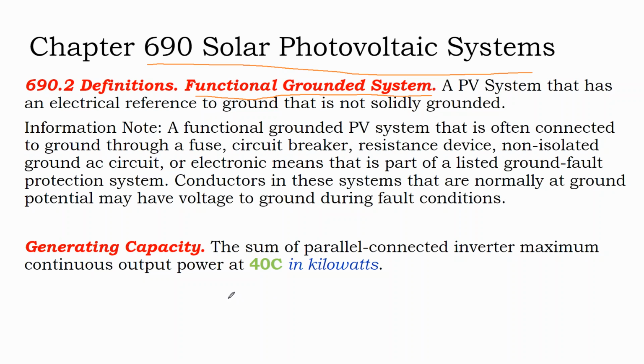Well, on a DC circuit, you would have a positive side and a negative side, and it's quite common to tie that negative side to ground so that the negative side has a voltage potential of 0 and the positive side has a voltage potential of 12. And so they'd say, well, that's negatively grounded.